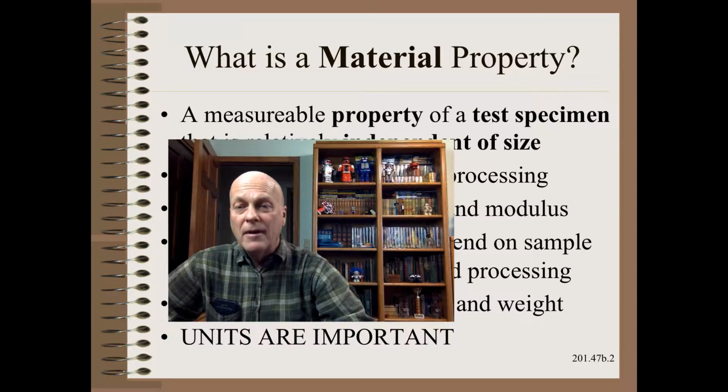Yet the proper engineering units for material strength are PSI in the U.S. system and pascals in the metric system. These could be obtained if you knew width and thickness and whether the tensile tester was already dividing by width before reporting. Very few people in the test lab know what units are actually being tested and reported. Sometimes you get really mixed units for strength, such as grams, a mass unit, and not even force, per 1 inch wide sample.